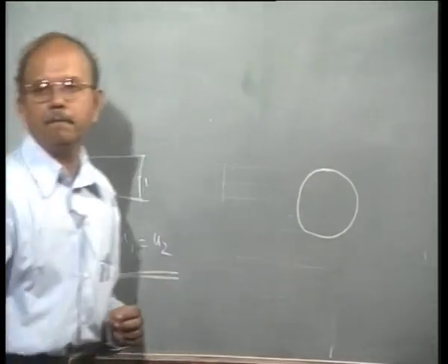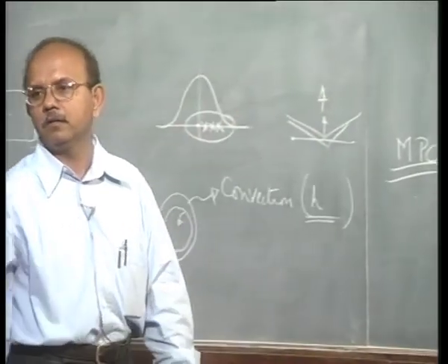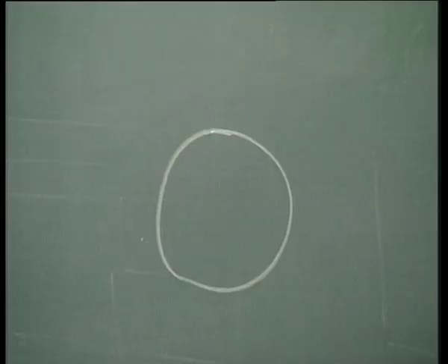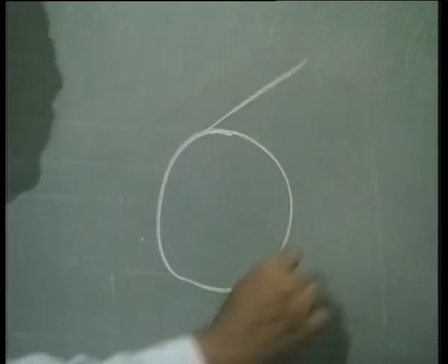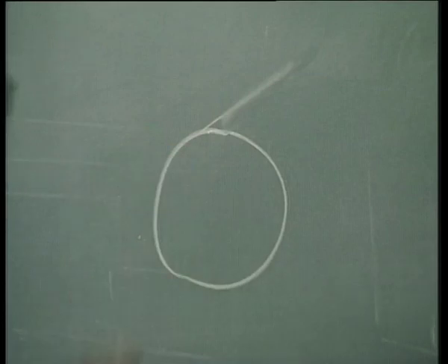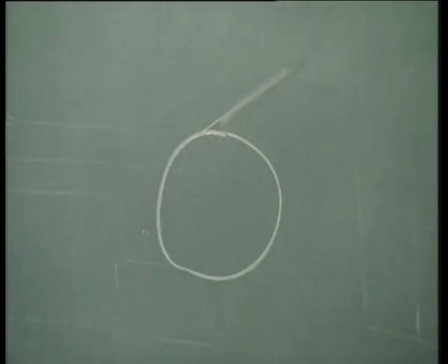There is a cylindrical piece. You are looking through the board, or in other words, the cylindrical piece extends like that, and you are looking at it from one end. This piece is made by the powder metallurgy (PM) process. Now this piece has a density which is, say, 90% of the theoretical density, say 90% of 7.8.